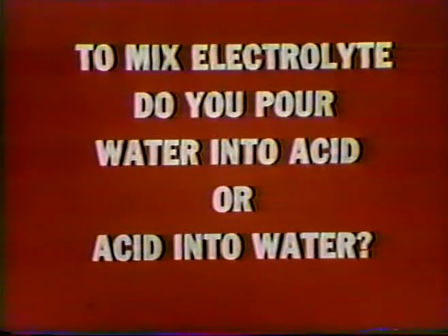Question: when mixing battery electrolyte, do you pour water into the acid or acid into the water? The acid is always poured into the water.